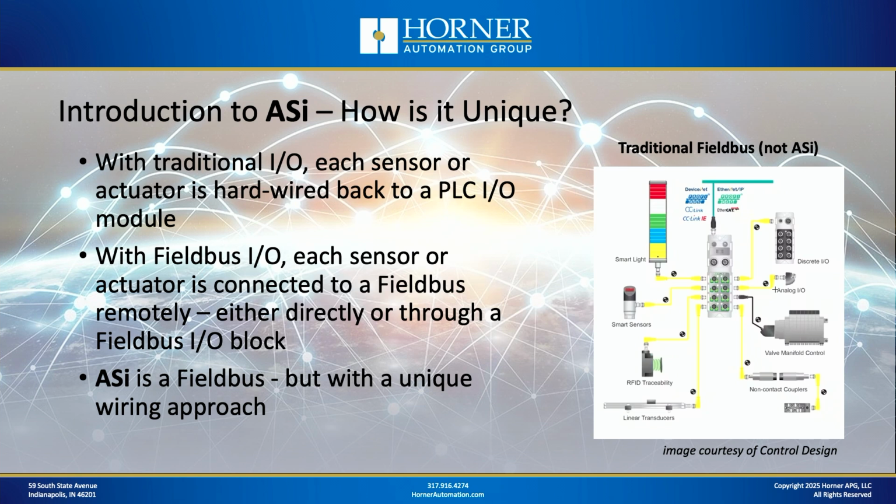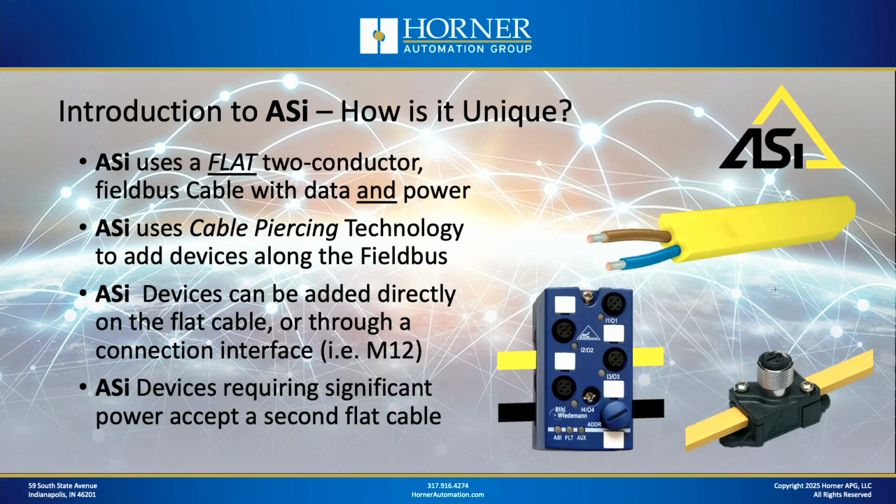Now, field buses were invented to reduce some of that wiring effort, especially when it came to remote I/O. Okay, so with field bus I/O, every sensor or actuator is connected to the field bus remotely, either directly to the field bus, as some intelligent devices do, or maybe through a field bus I/O block. Now, ASi follows that field bus approach, but with a unique wiring scheme. Let's start talking about that now.